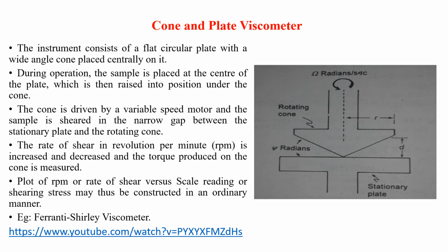Now, we need to plot a rheogram by taking shear stress on x-axis and rate of shear on y-axis. Do always remember, rate of shear is always expressed as RPM, revolutions per minute. That can be easily read from the scale or the monitor of the instrument.